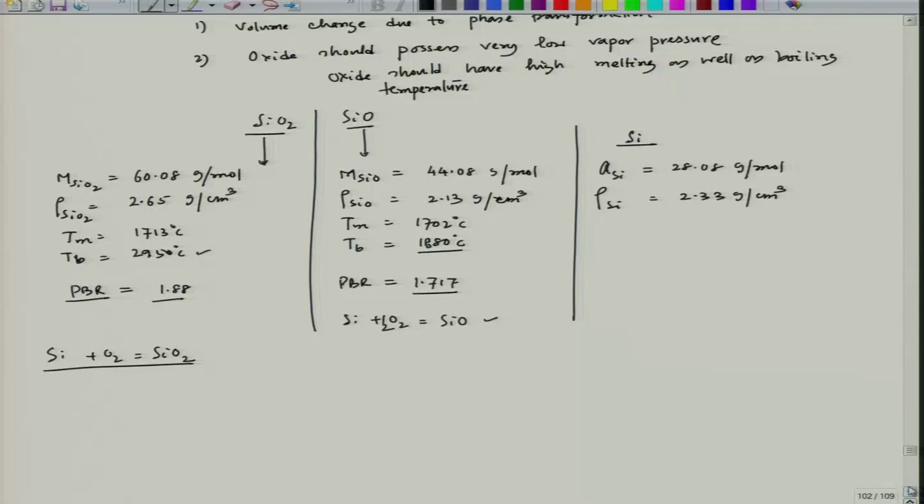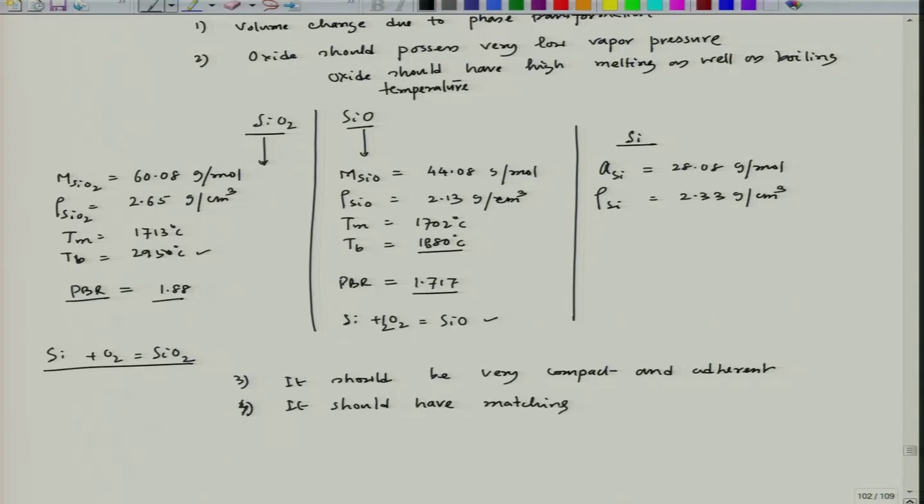There are other factors. For an oxide to be protective, it should be very compact and adherent; third, fourth, it should have a matching expansion coefficient, or I would say thermal expansion coefficient.